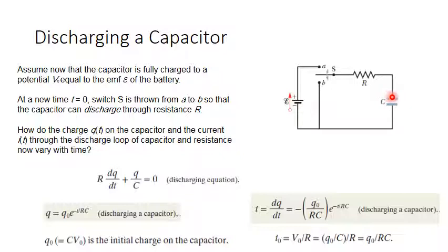So I have, for example, 10 positive charges here. One has passed from here to the 10 negative charges here. So one of the positive charges is neutralized with one of the negative charges. So the remaining here is 9 and here 9. Then another one is going from here to here. So it would be 8, 8, and so on. There is no pump inside the capacitor which can create new positive charge to make it continuous. So the charge will decay, and this decay is exponential. Okay?